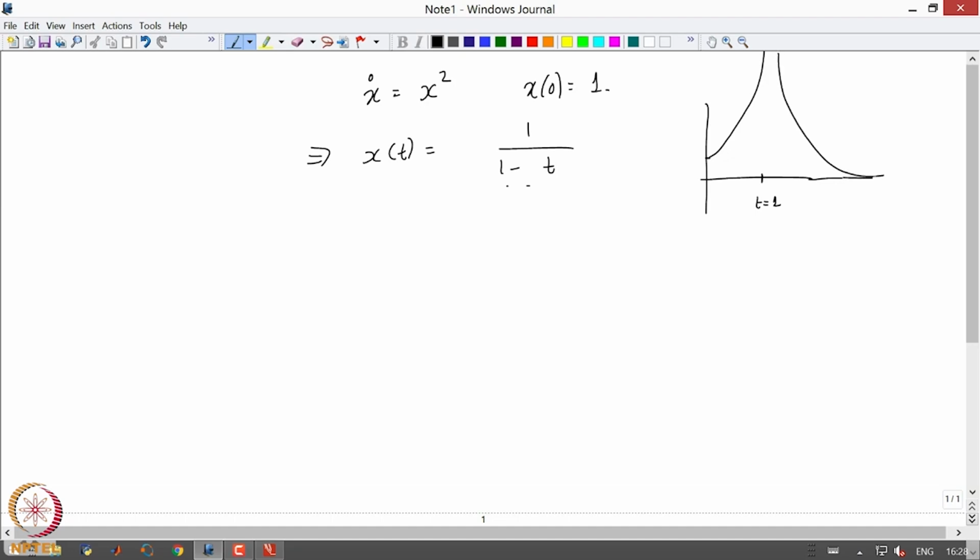Okay. Now, is this a stable behavior? Well, this is not, because the solutions actually go unbounded. So, what was the definition of stability? That whatever the solutions do, they should just be bounded above by some number. Okay. This typically could happen in some nonlinear systems, and this phenomenon where at t equal to 1 the system blows up is called the finite escape time.